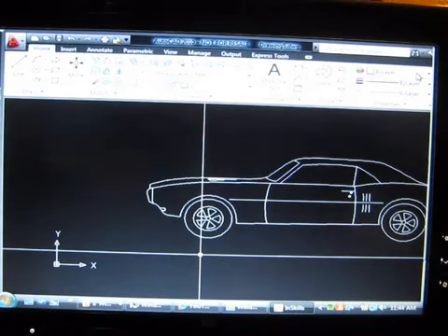Last tip of this section, press the up arrow key. That's the last command I used. That's the command I used before that. The arrow keys will scroll through all of your latest commands. This is very handy if you need to go back and forth between a few commands. Just scroll through it until you get to the command you want and press enter. The real key to AutoCAD efficiency is doing less work. The less you have to do, the quicker you can get it done.